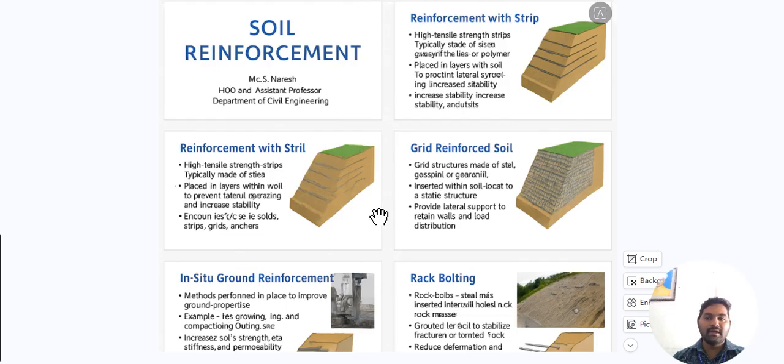In this example, there is black cotton soil. Black cotton soil is unable to bear the load because of montmorillonite, so large swelling and shrinkage take place, and settlement also takes place. At that moment it's not supported. If you want to construct heavy or high-rise buildings, then we need to introduce soil reinforcement. We need to cut the soil, place the reinforcement, and then fill the soil and give compaction, and then repeat the process until it reaches the top surface.